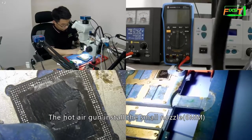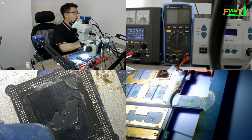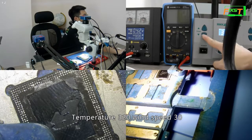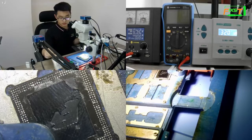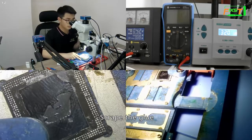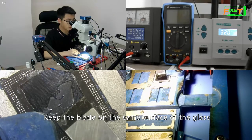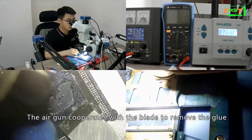Install the small nozzle in the hot air gun. Temperature 320, wind speed 30. Scrape the glue. Keep the blade on the same surface as the glass. The air gun cooperates with the blade to remove the glue.